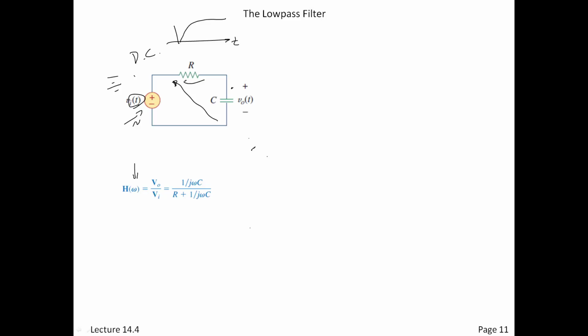And so you're just dividing the voltage between the resistor and the capacitor. And that's all we've done here, right? Here is the impedance of the capacitor. This is equal to Z sub C over Z sub R plus Z sub C. All right, there's no real fanciness here that says, oh, now we're not doing simple divider networks or current dividers or voltage dividers. All of that stuff is still present, and you need to keep thinking about it that way.